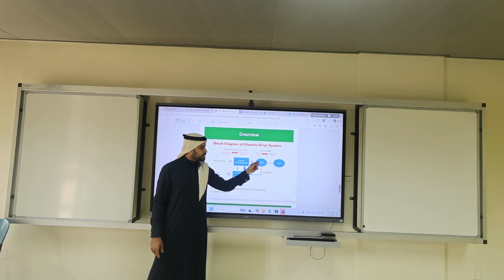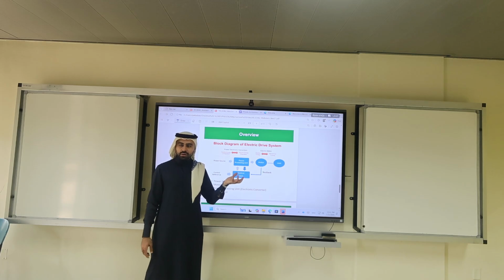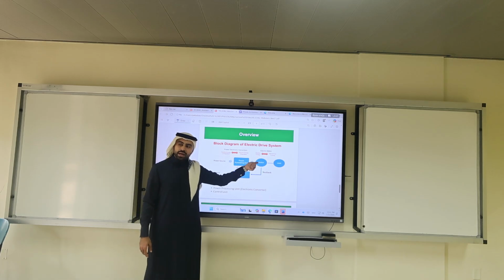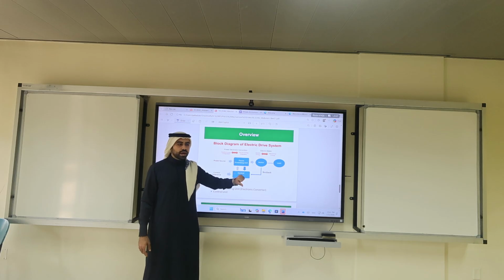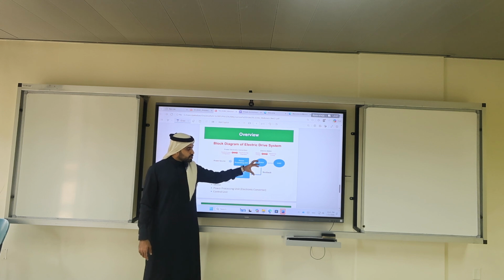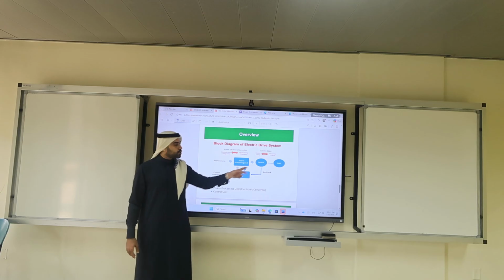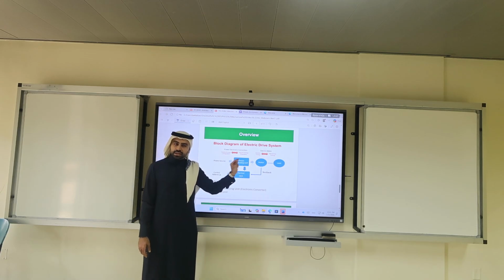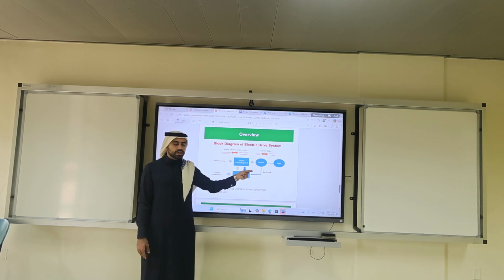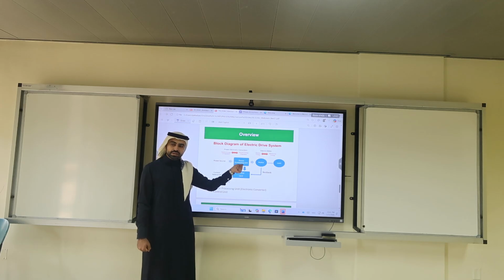So this load, for example, can be a gearbox that is connected to a fan. Now, if the load is heavier, the speed of the motor will be smaller, right? But the torque will be higher. The torque will be higher, the speed will be smaller, so we need to control this machine in order to have this power. Power is usually, in electric machines, related to the amount of current injected in the machine. So a high torque machine means high current is being injected from the power processing unit.